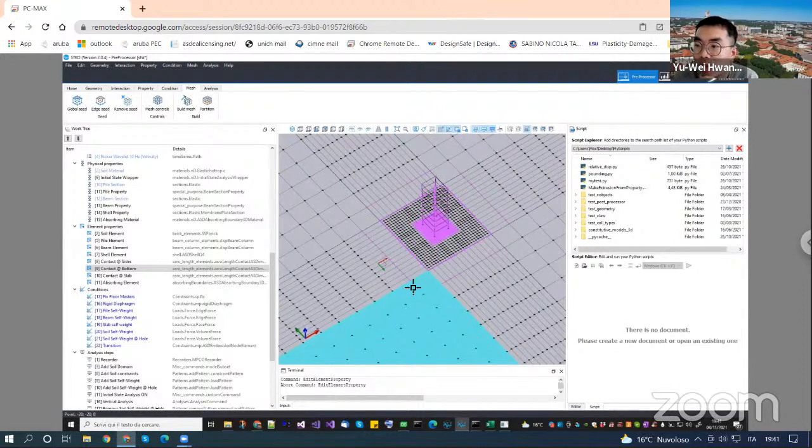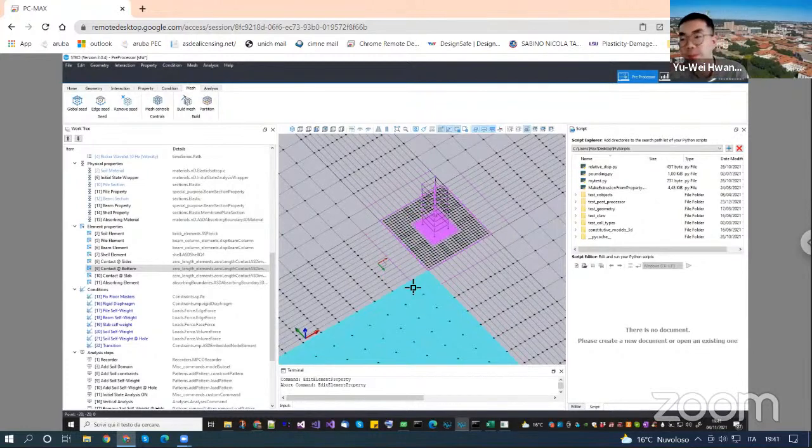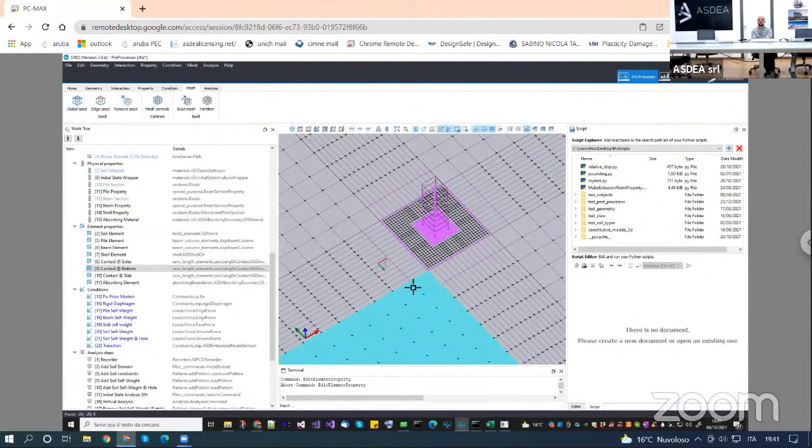The backbone curve is the reference one. But then, if you have pressure dependence, what happens? It's not that one actually. The problem is that it will depend on the soil model that you use, so you cannot find a unique solution. The main problem there is how to evaluate the nonlinear G modulus.